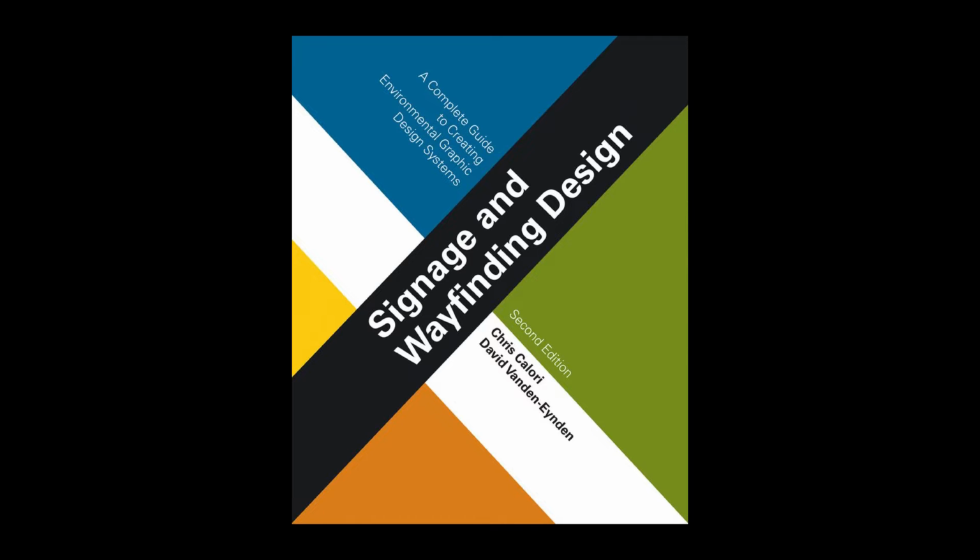Plan views depict the lateral footprint or perimeter of an object as viewed from the top. Sectional views expose the internal parts of an object, depicting slices cut through an object either lengthwise, longitudinal, or across, transverse, just as a carrot can be cut along its length or across it, with the resulting slices exposing the carrot's structure differently with each direction of cut.